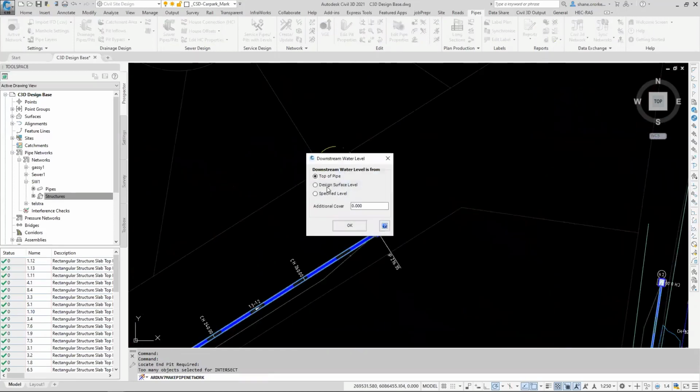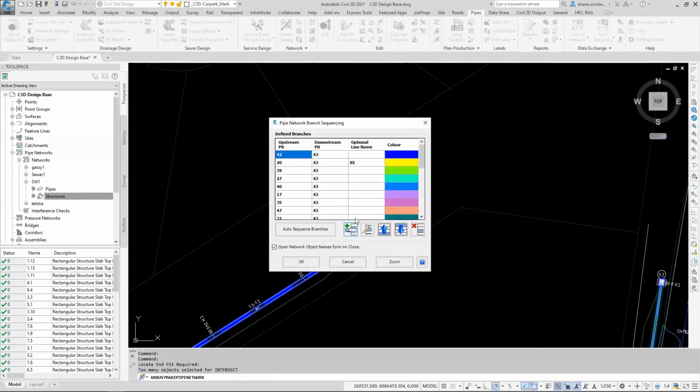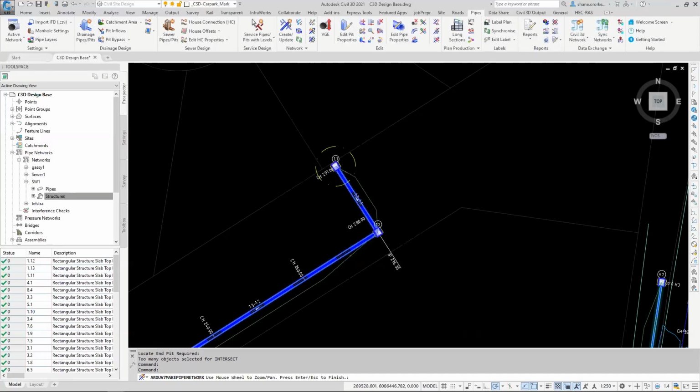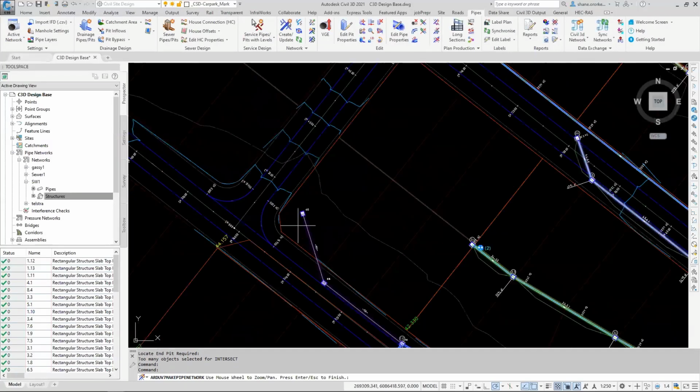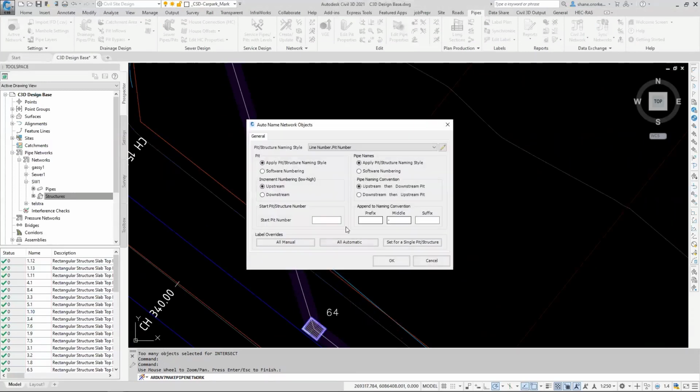So yeah, if you've added some catchments and put a flow through your Civil Site Design network, then that flow data will be added to the pipes in Civil 3D. And that means that on your Civil 3D profile view, you can show the hydraulic grade line also.